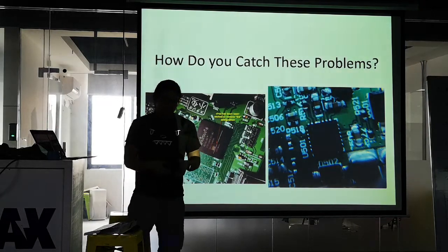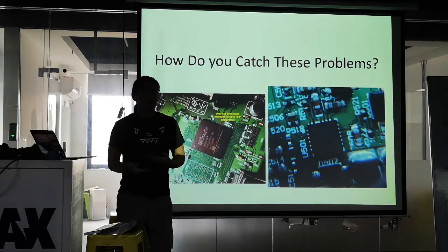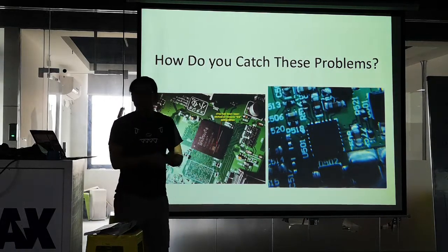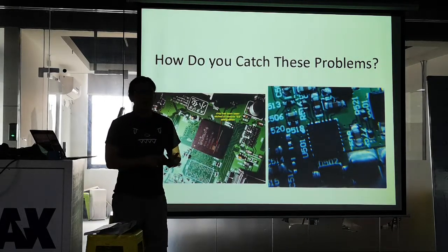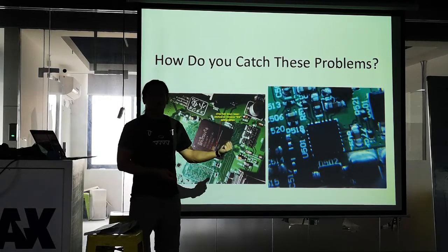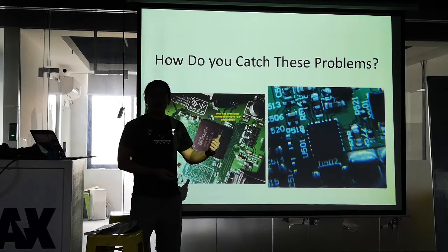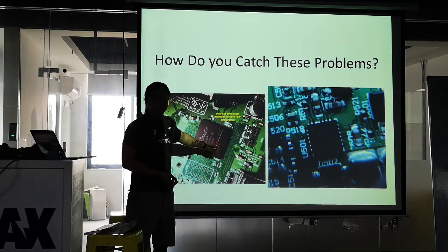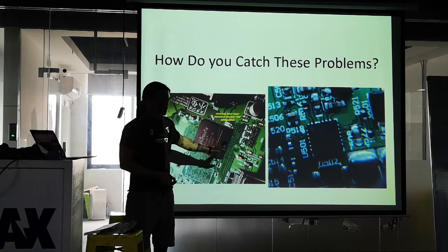And later on, I got the boards back. And I'm like, what the heck is going on? I can't figure out what's going on. I hooked up the JTAG to the FPGA so you can read out all of the parameters, the silicon ID code. It turns out the silicon ID of this chip didn't match the chip that I thought I was putting down. And then when I put it on a microscope, I noticed there's this white rectangle right here on the chip, right?